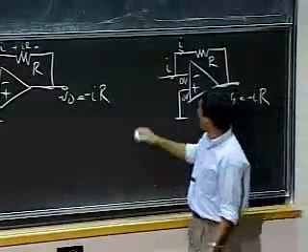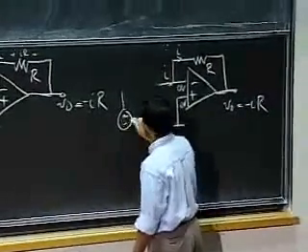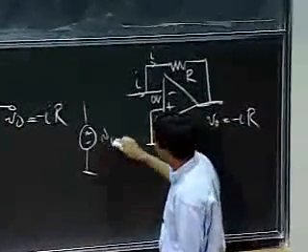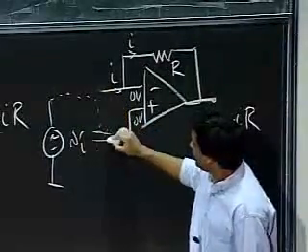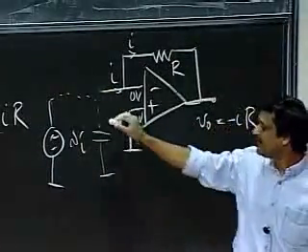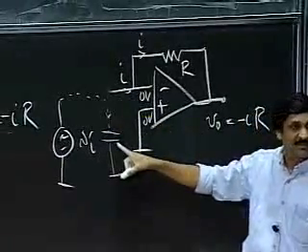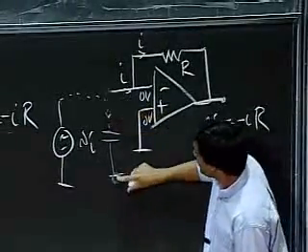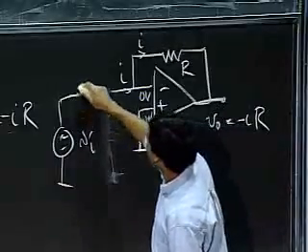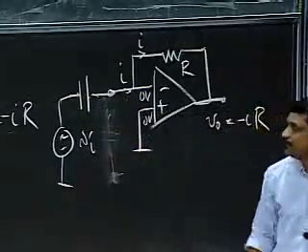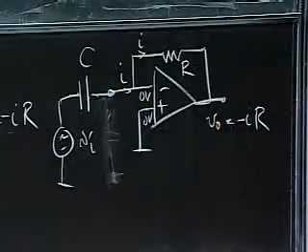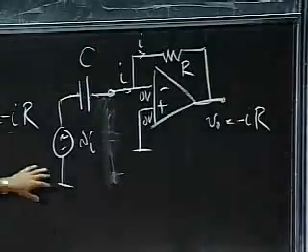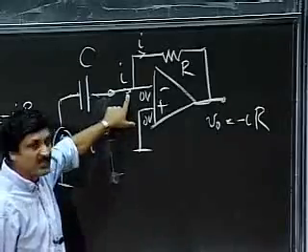So the poor little capacitor doesn't know the difference. I have really suckered the little beast. So this is VI. Remember this. My I through the capacitor is proportional to C dV dt. Instead, what I've done is taken this guy and stuck it here to get something like this. Just remember these 4 or 5 little tricks, and you apply them in op-amp circuits again and again and again. So this is VI. This is my virtual ground.